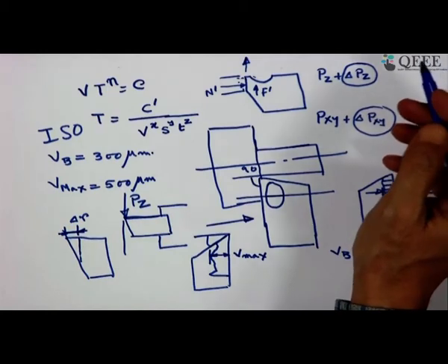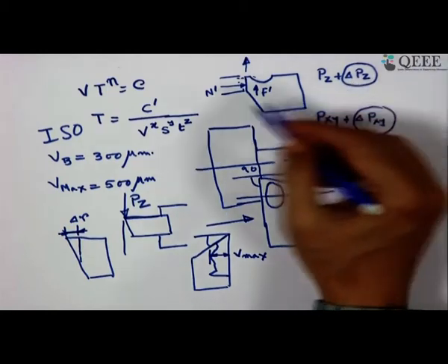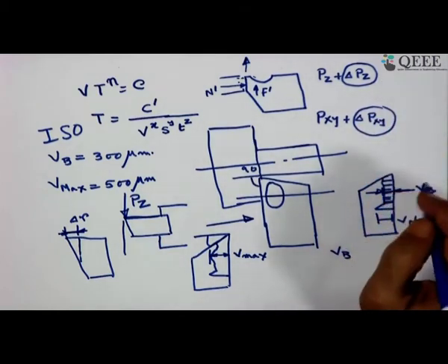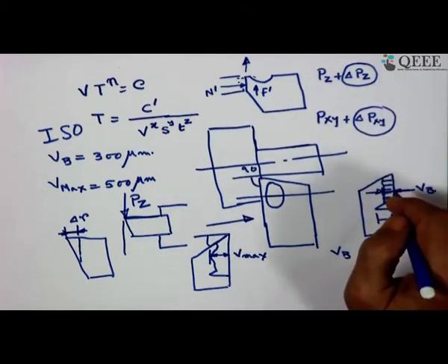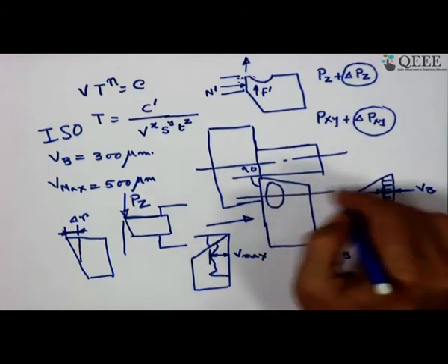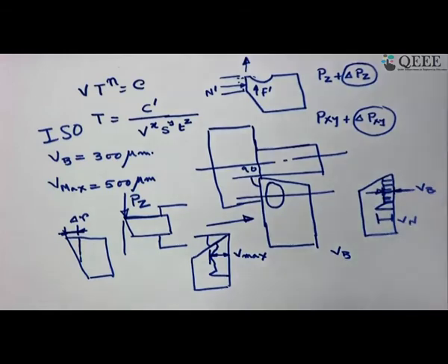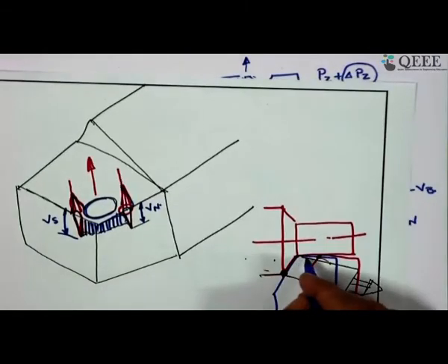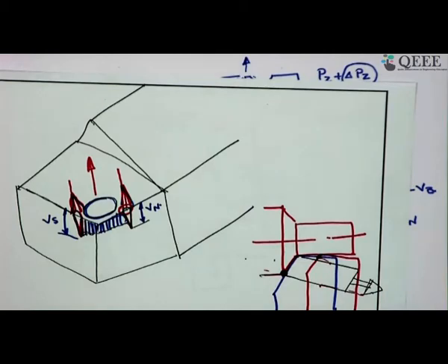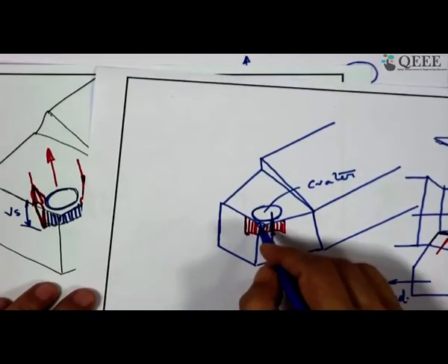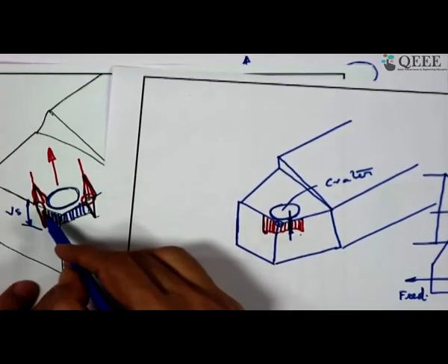So, for these two counts we must pay attention to this tool wear, and if the tool worn area is rough, it is having a direct contact with the job. So, finished surface will be spoiled. That finished surface we have drawn here, this one too also finished surface. I can show you that this is the wear on the auxiliary side, this you can see, this is also the wear.